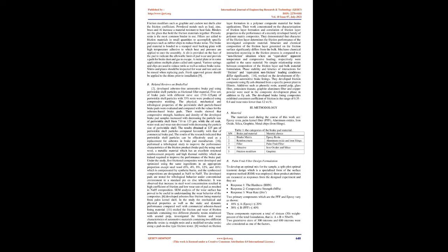In disc brake applications, there are usually 2 brake pads per disc rotor, held in place and actuated by a caliper affixed to a wheel hub or suspension upright. Although almost all road-going vehicles have only 2 brake pads per caliper, racing calipers utilize up to 6 pads, with varying frictional properties in a staggered pattern for optimum performance. Depending on the properties of the material, disc wear rates may vary. The brake pads must usually be replaced regularly, depending on pad material, and most are equipped with a method of alerting the driver when this needs to take place.